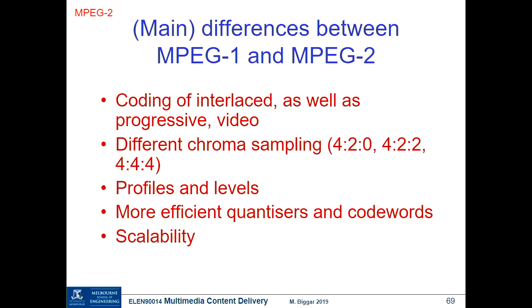They wanted to allow for high resolution chrominance. So instead of just 4:2:0, and we recognise why we want 4:2:0 to deliver to an actual display for someone to look at, they allowed for these higher resolution chrominance samplings because that was good for maintaining the highest quality when you're going into an editing process before you generate your final program.